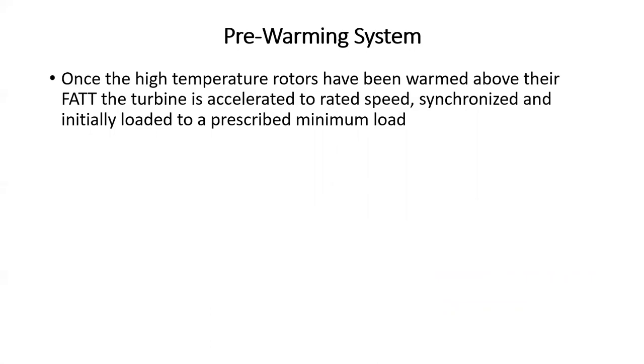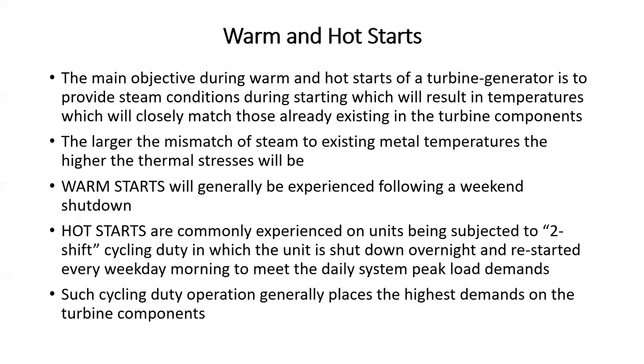Once the high temperature rotors have been warmed above their FATT, the unit is accelerated to rated speed, synchronized, and initially loaded to whatever the prescribed minimum load would be.